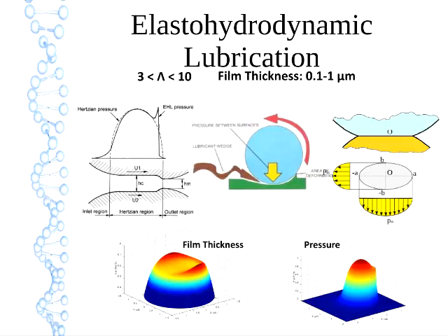The bottom two, so the top left, that shows the pressure and film thickness for a Hertzian line contact. So we're saying this goes infinitely long into the page, or roughly infinitely. And in the bottom, you've got it for a point contact. So on the left is the film thickness, and on the right is the pressure profile. So you can see that there's a lot of similarities.